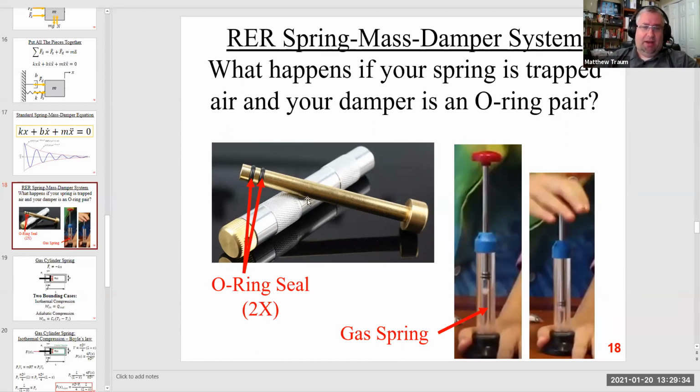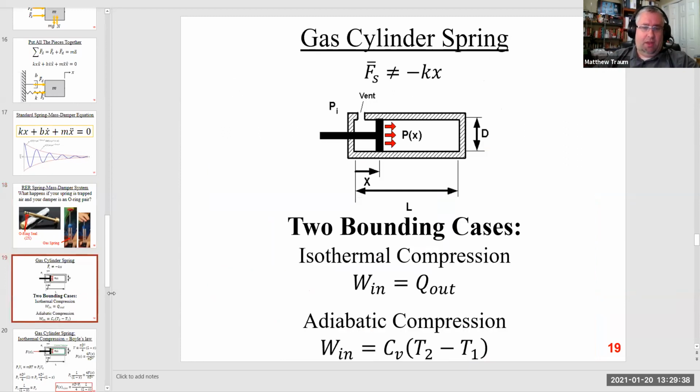But you could make it out of something else, like a really insulating plastic or foam, and then you would have a pretty close to adiabatic boundary. Or again, you could just do the process really fast. So there are two different ways to make the process adiabatic, meaning it's not transferring heat from the gas into the cylinder wall or the surroundings.